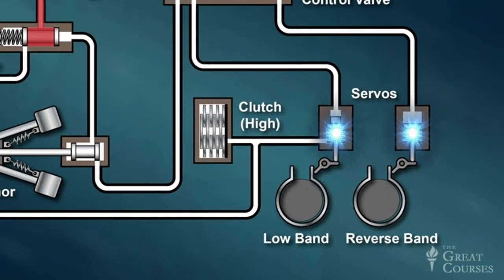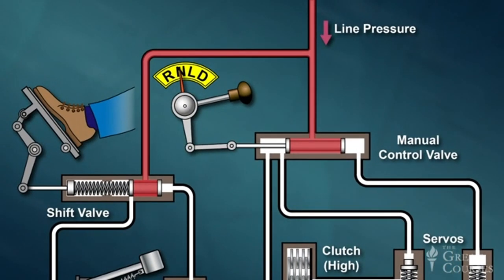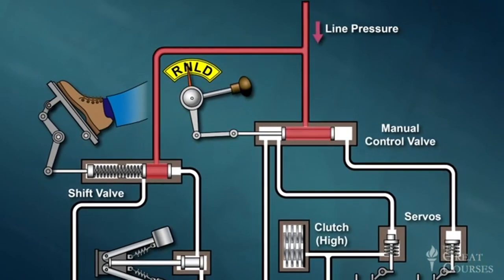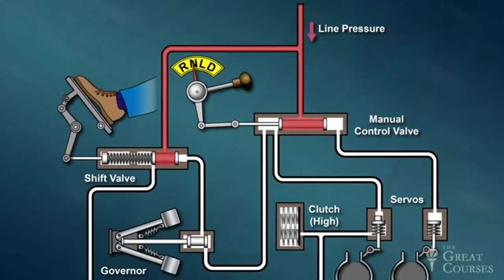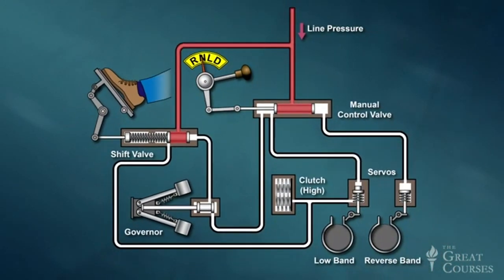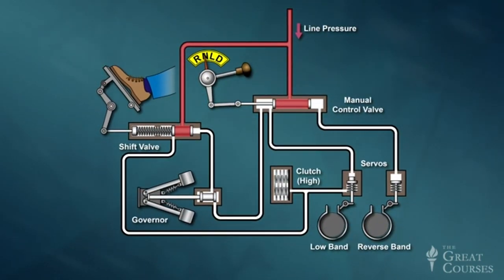Both of these are actuated by spring-loaded hydraulic pistons called servos; and finally, a system of hydraulic lines which receive high-pressure transmission fluid from a pump and transmit it through the control system in response to three different inputs: the shift lever position, the throttle position, and fluid pressure from the governor. Throughout this system, the presence of high-pressure fluid in any hydraulic line is called line pressure.